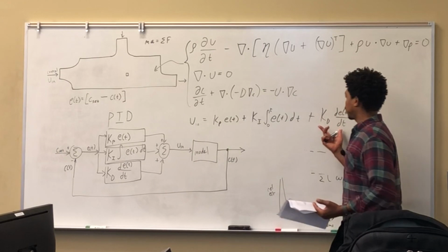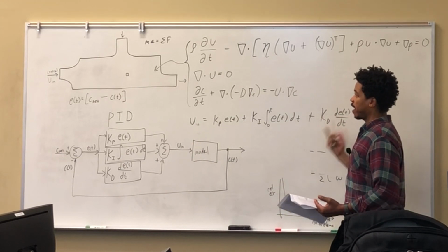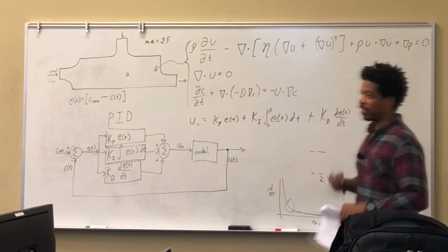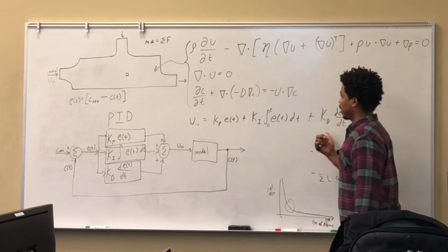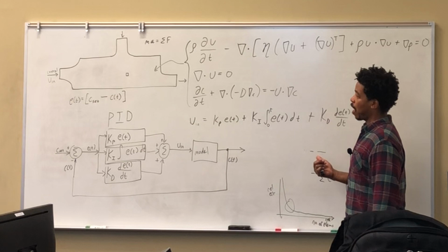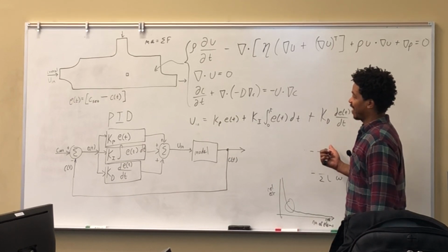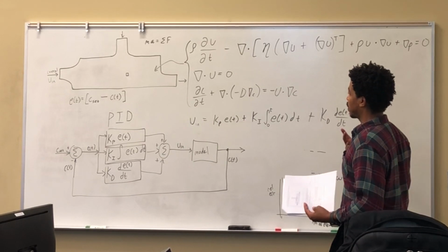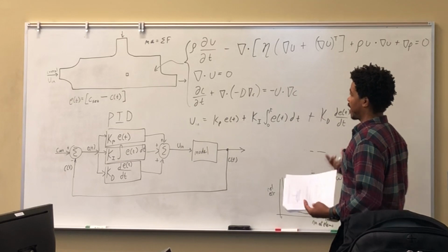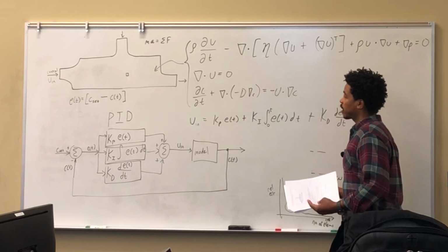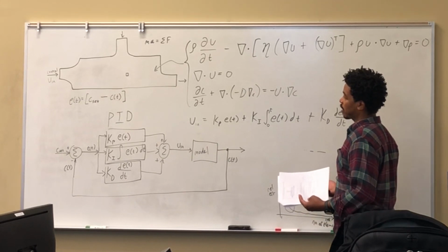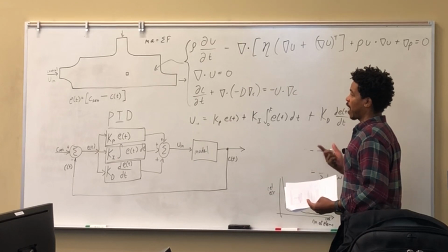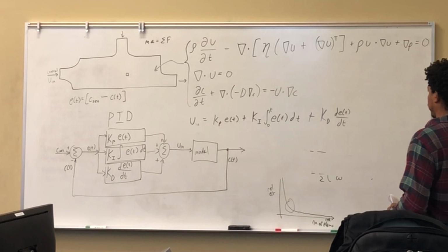And just practically speaking, a lot of times you want your feedback to happen very quickly because your system is changing very rapidly, right? In that case you want your feedback to be almost instantaneous, but we don't have that yet, right? There's always some type of delay due to the electronics. Most of the time the delay could be as small as nanoseconds, actually, okay? If you're using analog circuits. In digital circuits, it could be tens of nanoseconds to hundreds of nanoseconds. But if something is happening very rapidly, you want that feedback to get back as soon as possible. If not, you will have a delayed feedback, and that can cause some stability issues. Okay.